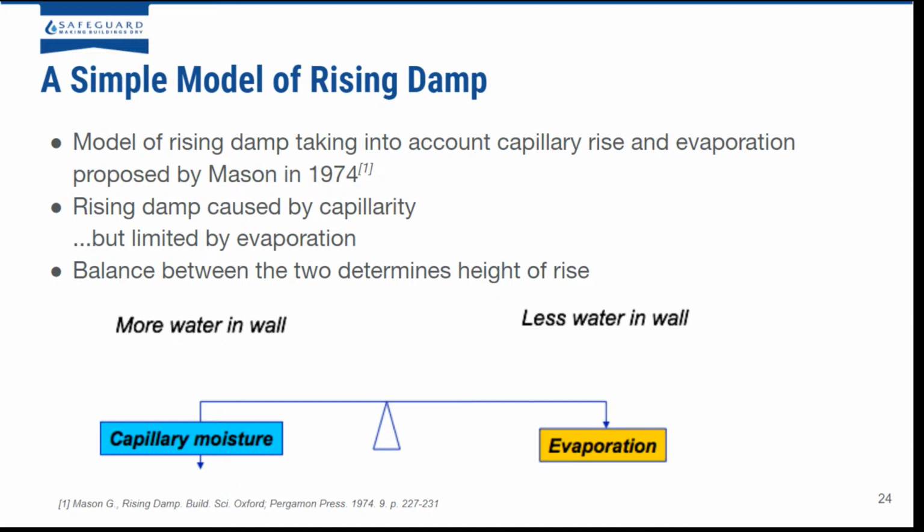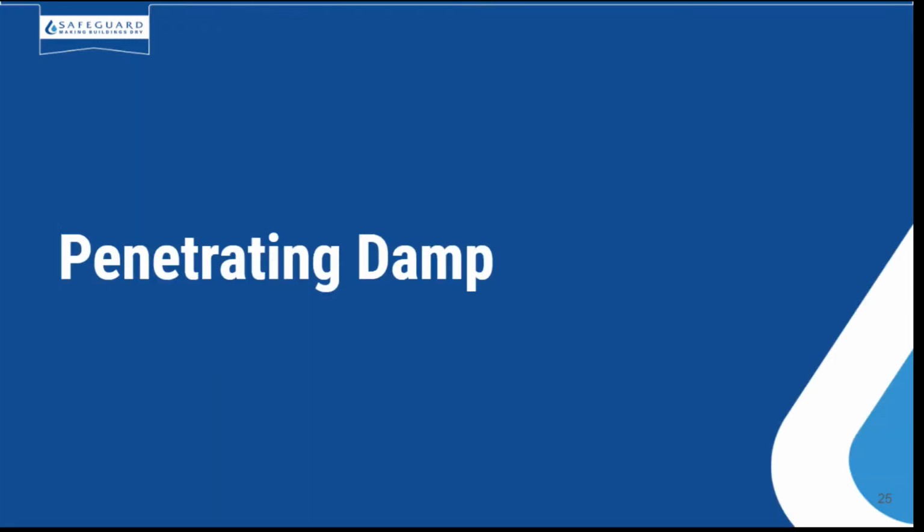Just on this rising damp situation, it's quite common for it to appear, and most kinds of dampness, especially after you've done some form of renovation work or even retrofitting, because you've effectively changed the wall structure and the permeability of the wall. Yep, you've either bridged it or changed the evaporation or how the dynamics of that building element are working. So it's really the time when you'll see issues with rising damp, if you didn't already have them.